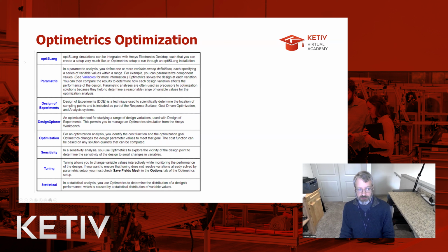And then finally, there's one last option here called optiSLang, at the very top. This is where optiSLang has these optimization tools, and you can think of it as optimization on steroids. When you have tons of variables, or a harder optimization problem, the optimization algorithms within optiSLang are designed so that, instead of brute forcing things and running 1,000 simulations to figure out where I need to play, it allows you to run only a few simulations, make some inferences, and reduce the total number of runs to get a similar result. So I might need 50 or 100 runs rather than thousands. This can save you a lot of time when you're trying to optimize.